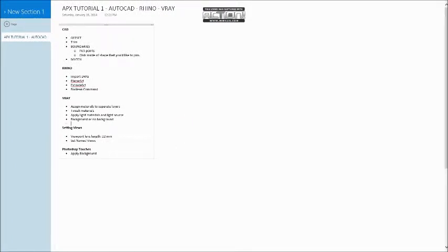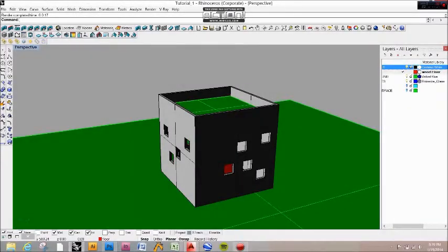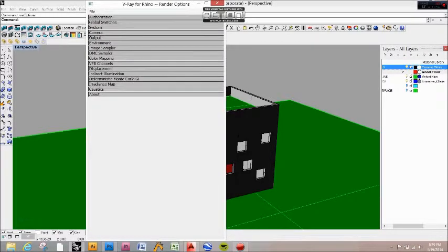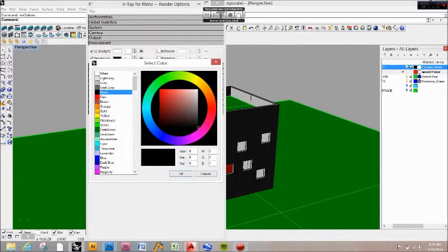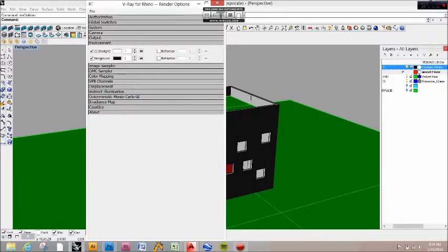Setting. Oh, okay. No background. So later on in Photoshop, you probably want to add your own Photoshop sky. So what you do, you go to V-Ray, Options, Environment, and you click the background off. Now sometimes, to get realistic renders, you might want to set up a blue sky color so that your whites can really reflect a normal day, like a photo.